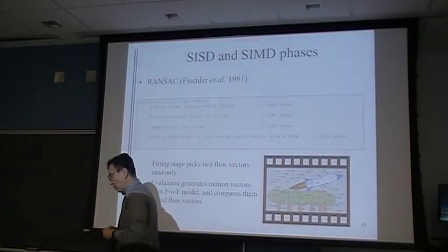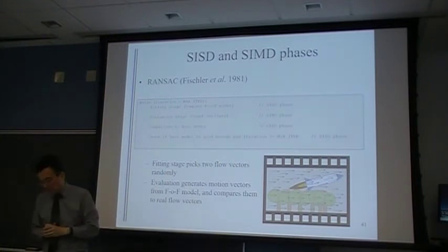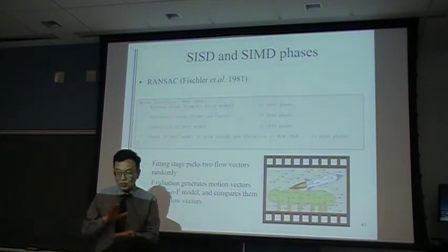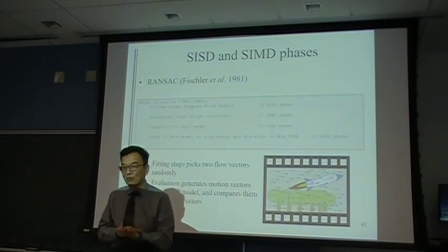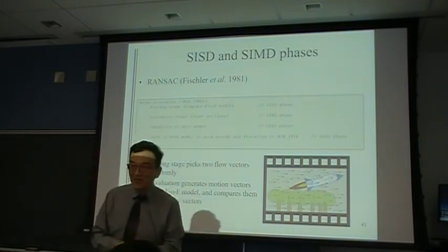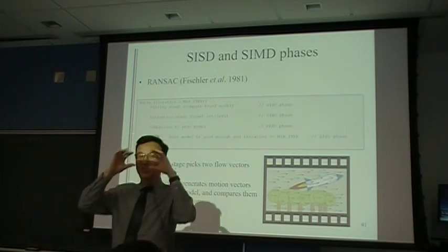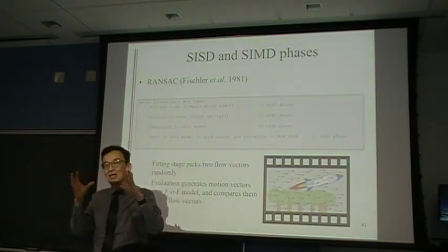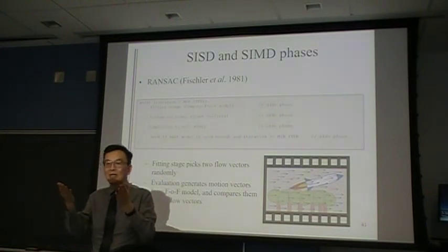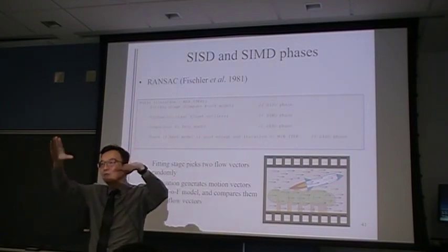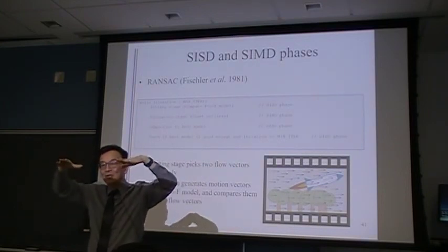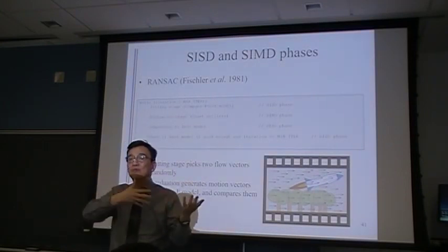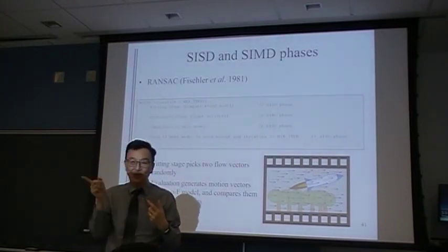And for some of these robots, there's also a motion compensation issue, because if you have a robot that is walking, the camera is going to be doing this. So you have these up and down movements. Can you tell that these objects are actually background objects that appear to be moving because your camera is moving, versus objects that are actually moving around, which are the ones you need to pay attention to, right?